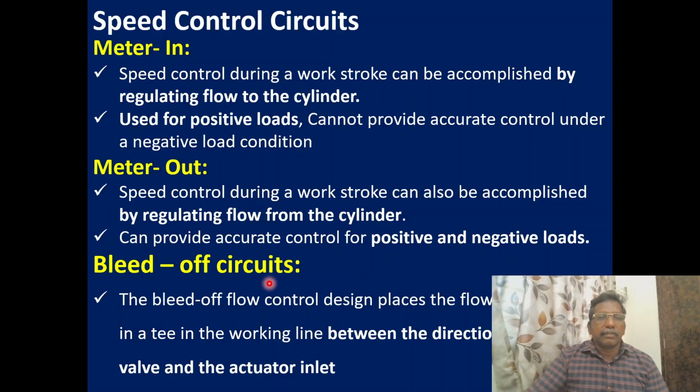The third one is the bleed-off circuit. The bleed-off circuit design places the flow control valve in a T in the working line between the direction control valve and the actuator.